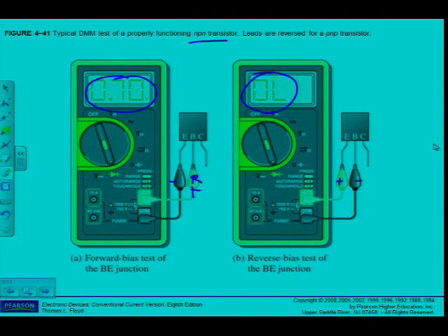That's the only reason. So if the internal battery of this multimeter is say 9 volts and it's still good, it should display a value of approximately 9 volts when it's reverse biased. So don't get confused. Some meters will show open line, some meters will show you the voltage of the internal battery.